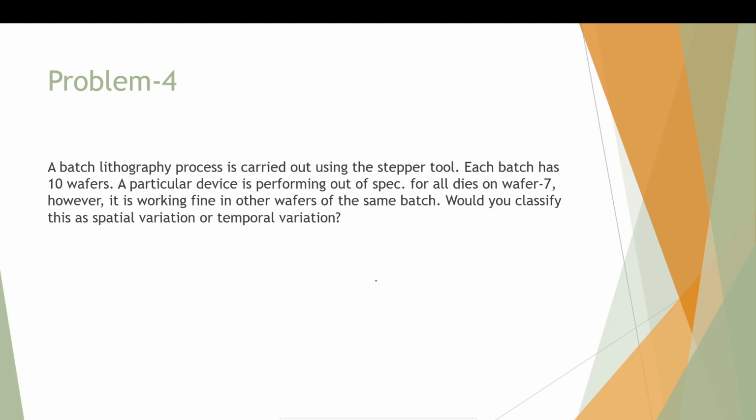Okay. A batch lithography process is carried out using a stepper tool. Each batch has 10 wafers. So in the stepper, at a go we are putting 10 resist coated wafers, and we are patterning all the 10. A particular device is performing out of spec for all dies on wafer 7. Say this is my wafer 7, it has multiple dies, right? So these multiple dies have multiple different devices. So one particular device is working faultily in all the dies.